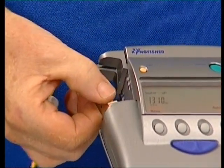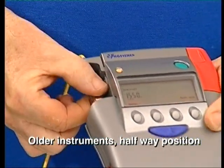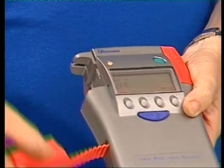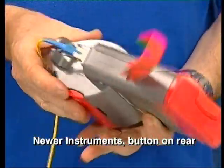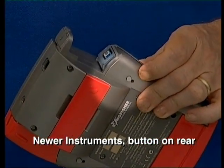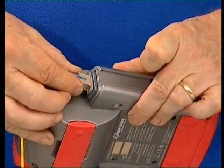On older instruments, the connector is rotated to a halfway or mid position, and then the adapter can be pulled off. On newer instruments, a button on the rear of the instrument is depressed and the adapter is pulled off. To replace the adapter, rotate the alignment slot the correct way and then push it in.